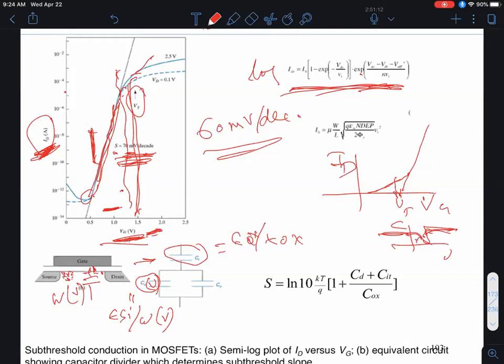Now, in addition to this capacitance, you also have what's called a fast interface state capacitance. I don't know if you recall that. We said that at this interface you'll always have some structural defects, and those will give rise to energy states in the band gap. So that's my EC, EV. When the bands bend, these interface states sometimes will move below the Fermi level, in which case they'll be occupied by electrons.